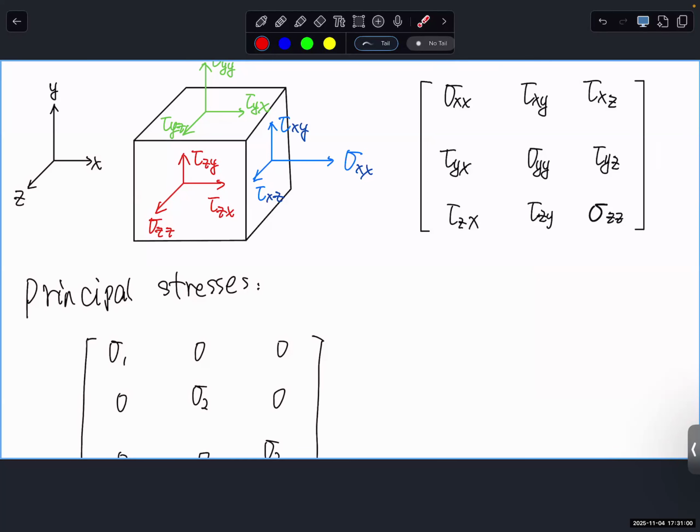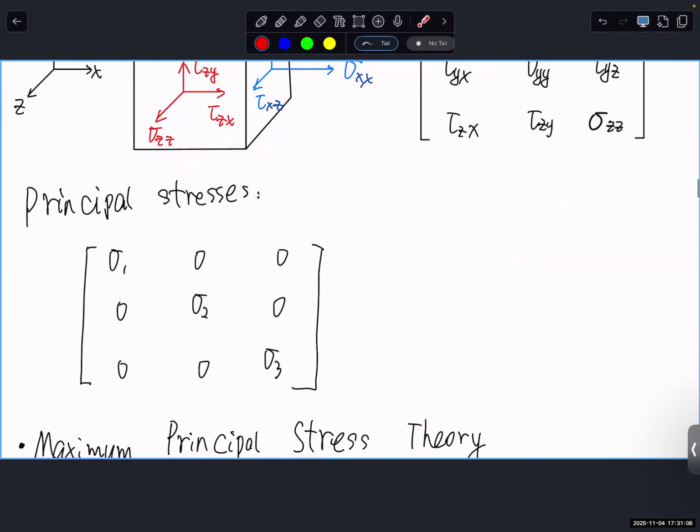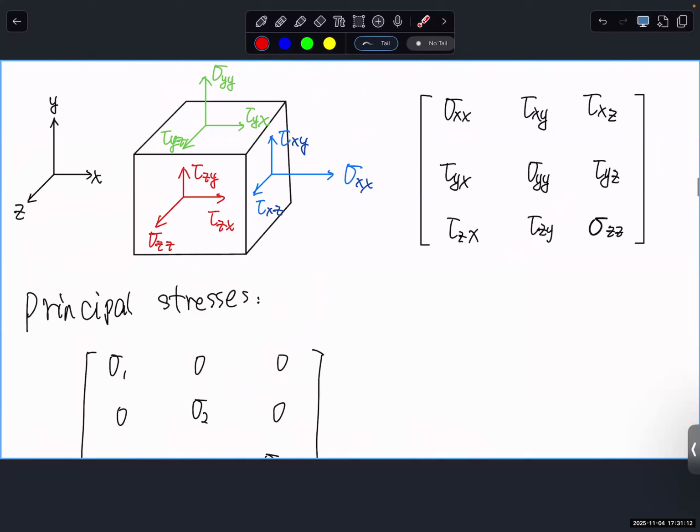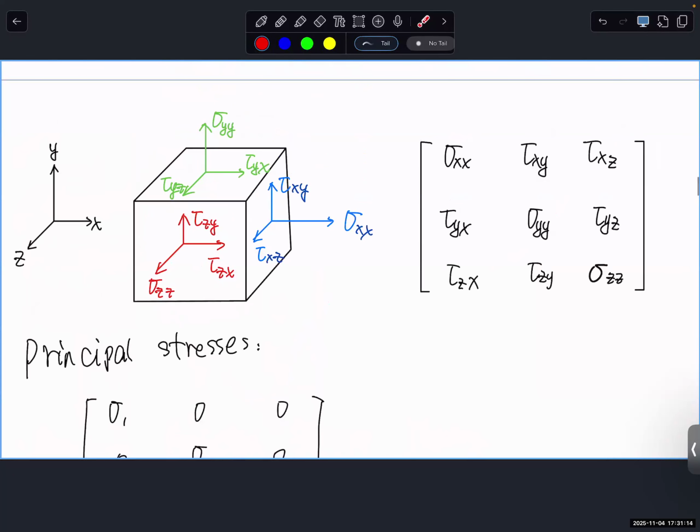And mathematically, how do we get the stress components in the global coordinates and find the maximum principal stress where all shear stress disappears? It's an eigenvalue problem. The eigenvalue problem, you probably learned somewhere before you came to this class. So you have the matrix minus lambda, minus lambda, minus lambda on the diagonal, and make its determinant equal to 0, and all 3 lambdas become the 3 eigenvalues of a 3 by 3 matrix. Make sense?